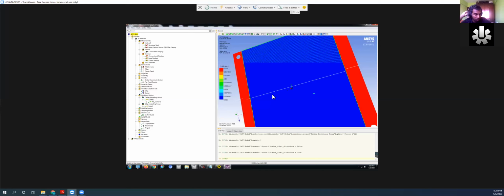So you want to just take a general look at it, make sure that all the lines are pointing in one uniform direction. It's okay if there's a few spots like here and here, but generally you just want an even parallel distribution of lines across the entire thing. That just shows that your fibers are laid correctly and how it's oriented.